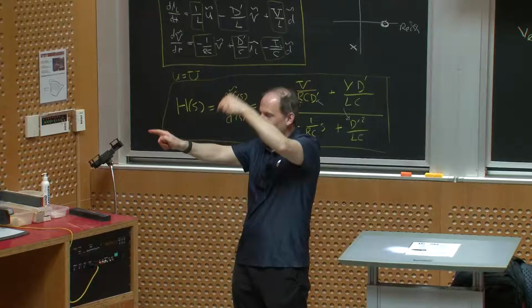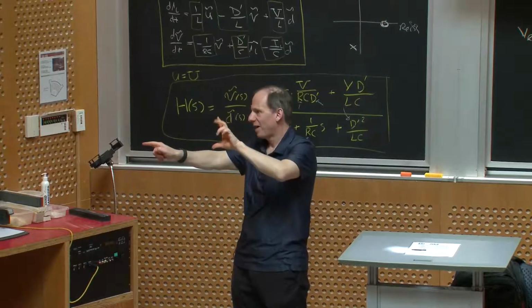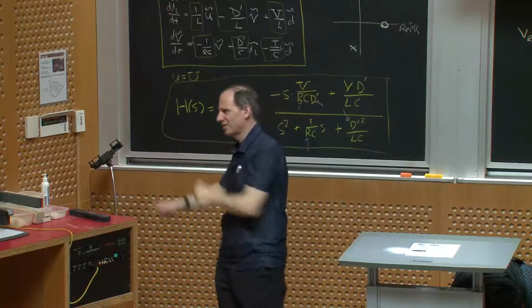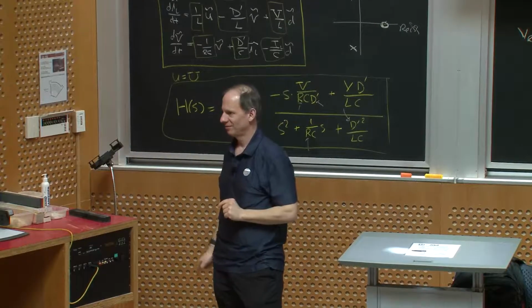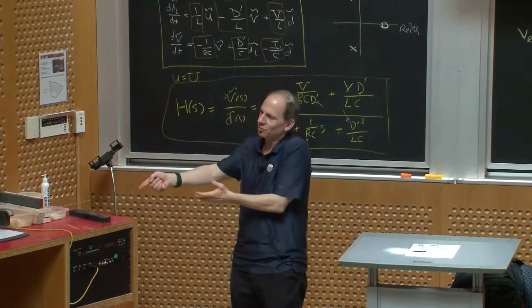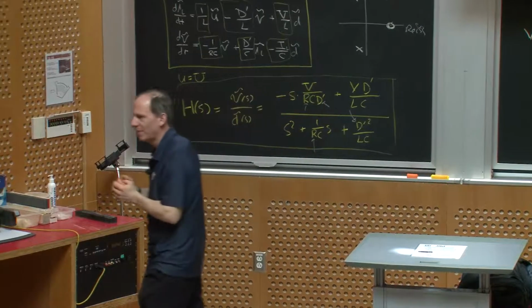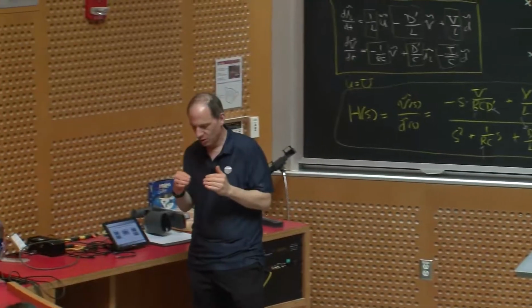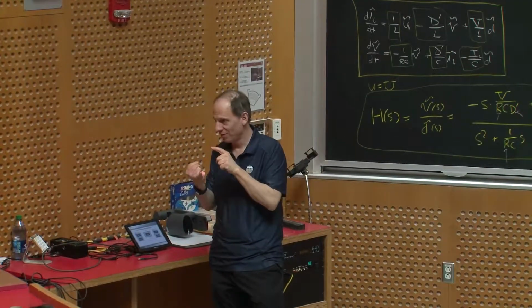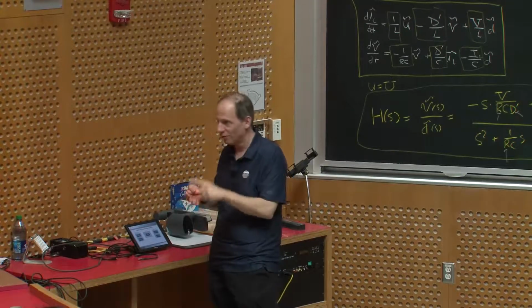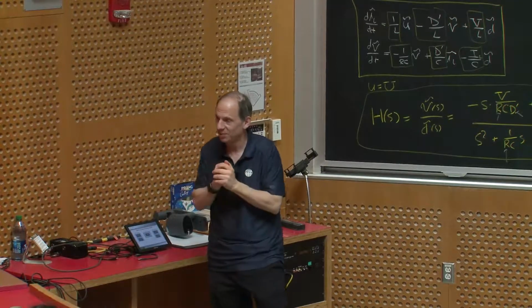And that little response may be bad. So if your power supply is wiggling around, a little bit of that gets into the output, and you don't like that, right? If what I'm feeding is a resistor, maybe you don't care. So it depends on the application, but a lot of the time, if it's a power supply for an instrumentation amplifier or for an RF transmitter or for a receiver or something like that, you've got to keep it very clean.